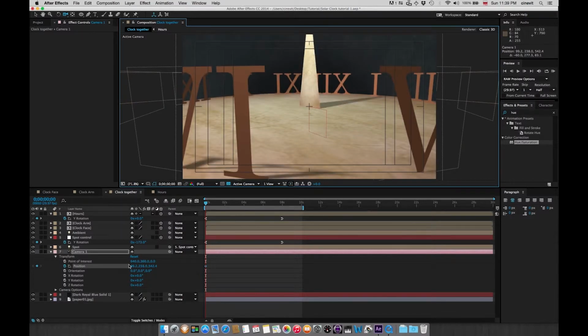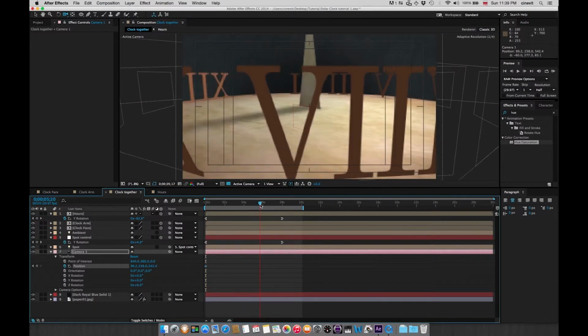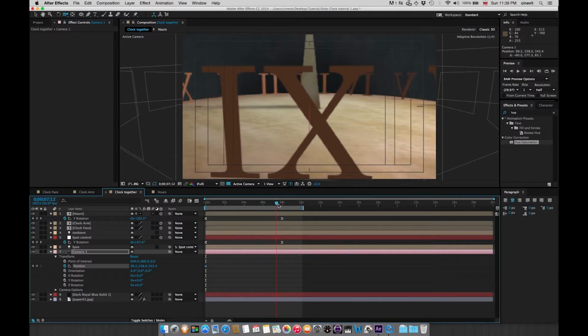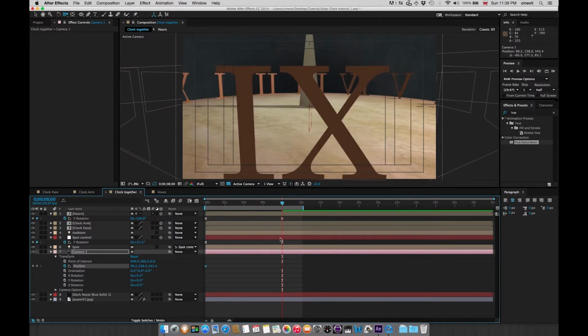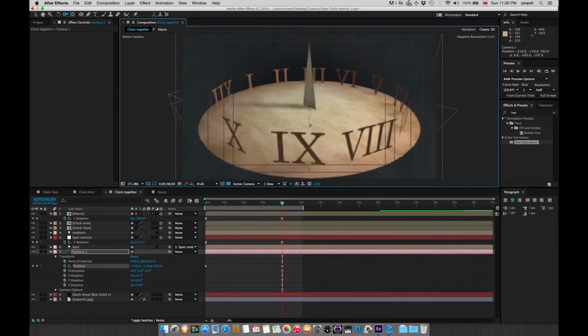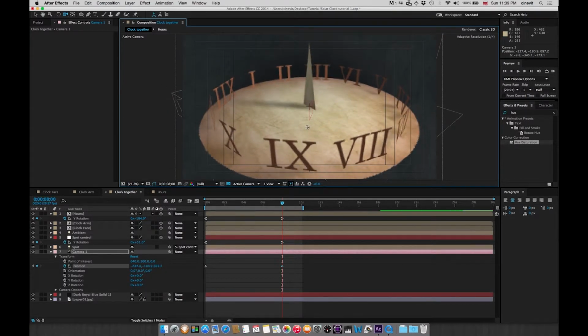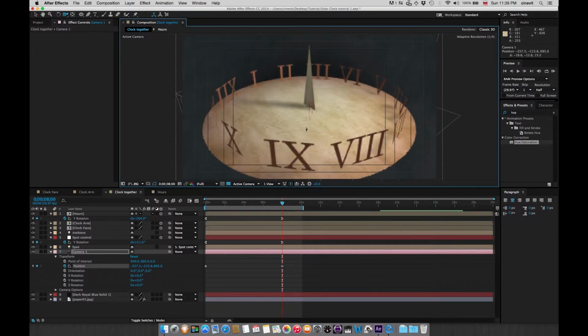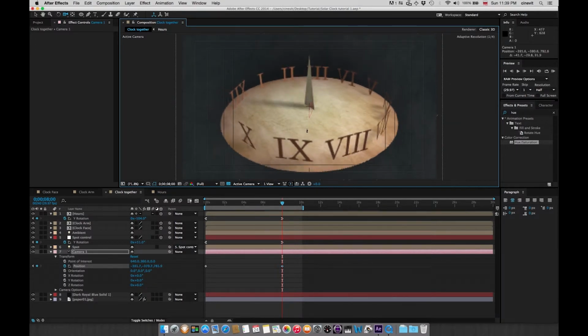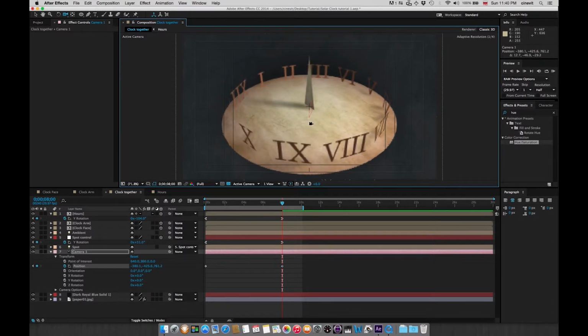So I think we started something like this, so I could see those letters here in the foreground. And so we have the keyframe here, and then I'm going to move my playhead and, with Shift, snap it to those two keyframes. Then again I'm using just track out, and I'm adjusting with the regular click, the orbit around, to just put it at the right angle. So it's in between those two, the track out and orbit, to just adjust its position.